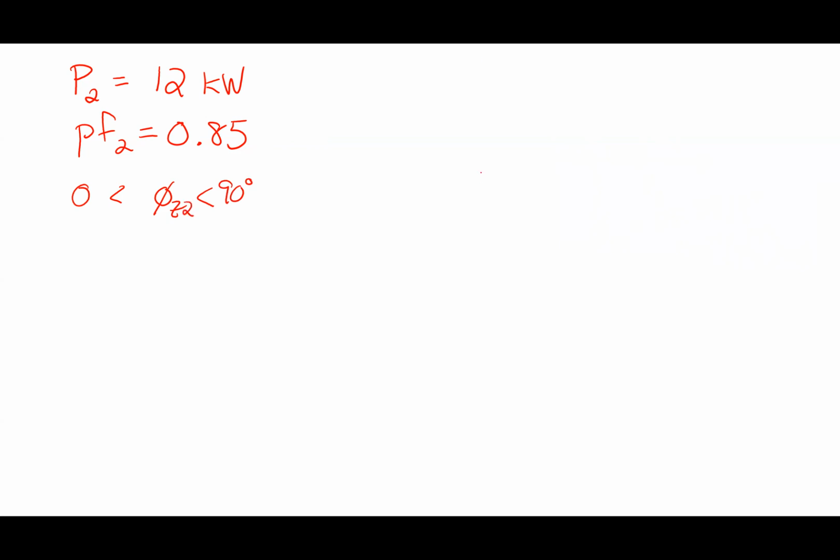In terms of that triangle, notice that in all these problems you're given two things about the load. You're given its angle somehow, since the power factor tells me the angle, and then you're told the length of one of the sides. From there, I can figure out everything else. So which side of the triangle am I given here?